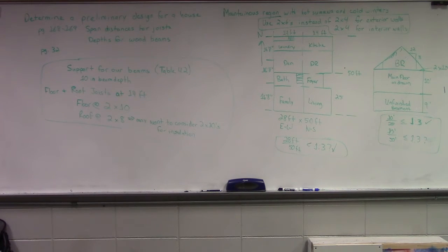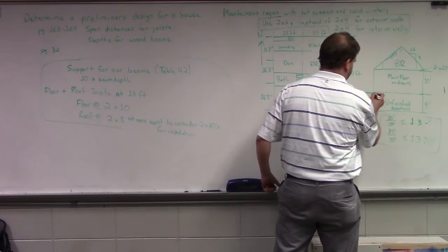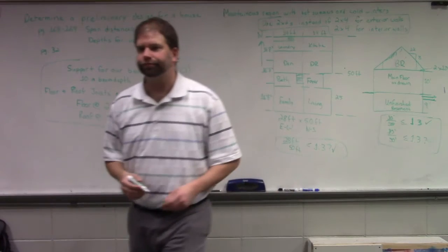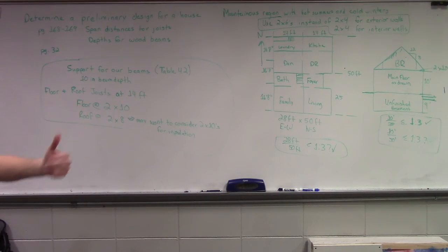So for a shear wall, what we're supposed to try to meet is that the shear wall panel should be continuous from the foundation to the roof. It's 2 stories tall, so you should take that 19 feet in. Oh, never mind. I keep looking at that, thinking that the 9 feet is the main floor. Your grade is probably somewhere in here. But yeah, if we had a 2-story building, the shear wall would run from the foundation, it's tall, and it would fit within that 1 to 3 at that point.